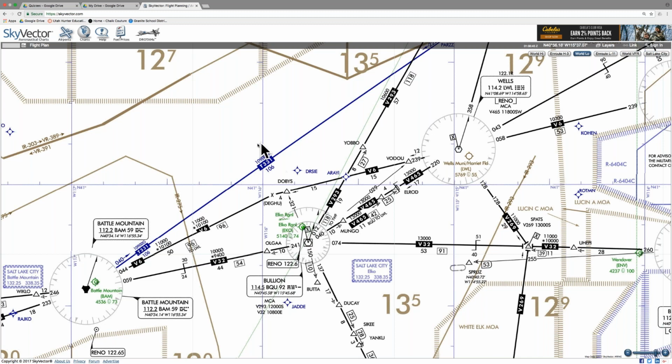Is the high elevation GPS? What's this one? Tango route. Yeah, T route. So it is a T route. Jet, Victor, Q. So a jet route isn't satellite-based navigation. That's using ground-based navigational aids. A Q route is. Yeah, a Q route. So T routes and Q routes.